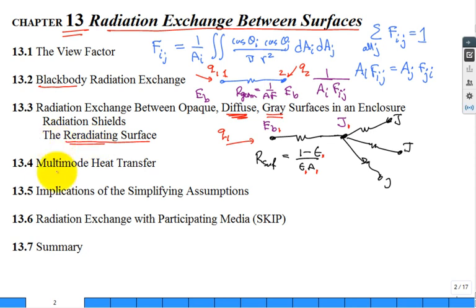Well, as soon as you have radiation down, you can couple it with convection and conduction heat transfer. Just have to be careful. What drives conduction and convection is a difference in the temperature. What drives radiation is a difference in E_b, or a difference in the temperature to the 4th power. So you immediately get some nonlinear equations, and you would use a computer program to sort it all out and solve for the roots of the coupled system of equations.